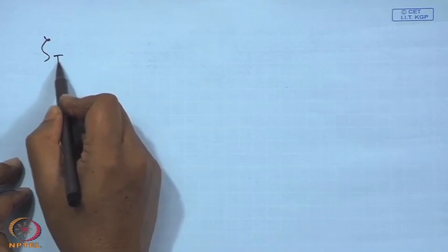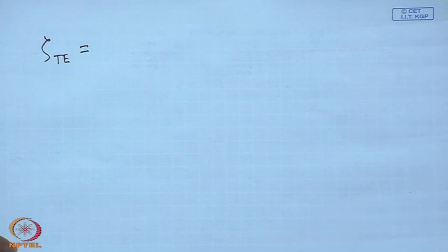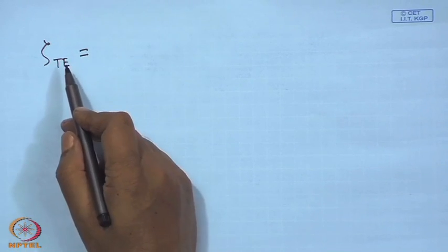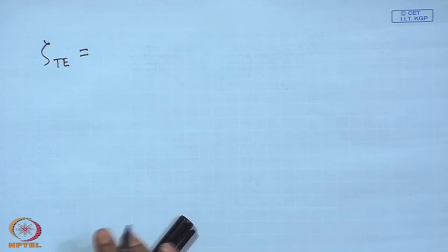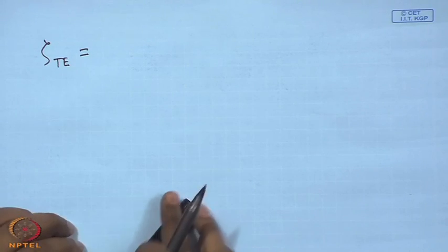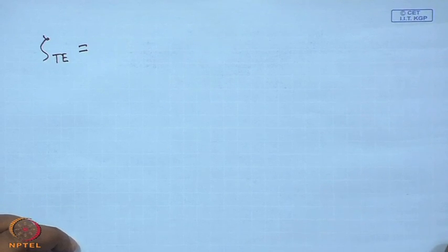The point on the circle that corresponds to the trailing edge of the airfoil is at an angle minus beta, and the critical point minus b is placed on it. So, how much is that? The point on the circle plane that corresponds to the trailing edge point as before is zeta trailing edge. Be careful about the interpretation of this point zeta trailing edge. Actually, the circle has no trailing edge. This is the trailing edge of the airfoil which corresponds to the point on the circle. It is not the trailing edge of the circle. A circle has no trailing edge.